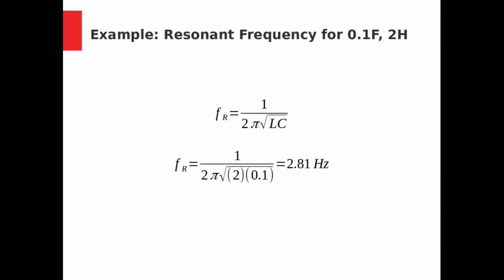As a parting thought, there is a condition for AC-RLC circuits called resonance. In resonance, the effect of the capacitor and the inductor cancel each other out, and the current returns to being in phase with the voltage. For this to happen, you have to change the frequency so that the capacitive reactance and the inductive reactance are the same. This equation shows you the resonant frequency of any AC circuit.